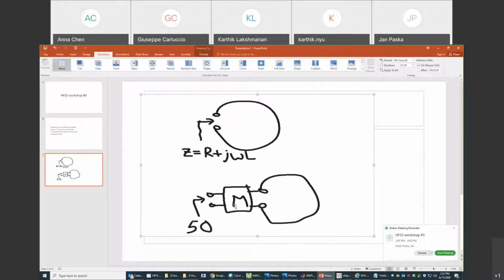And for that, you usually need 2 degrees of freedom. One way to do this is by using fixed value capacitors to match to 50 ohms. Another way to do it is by co-simulation, and do this matching in a post-processing step.